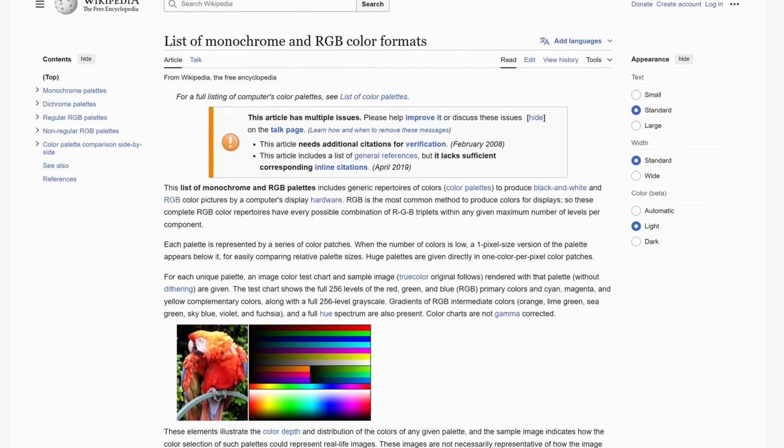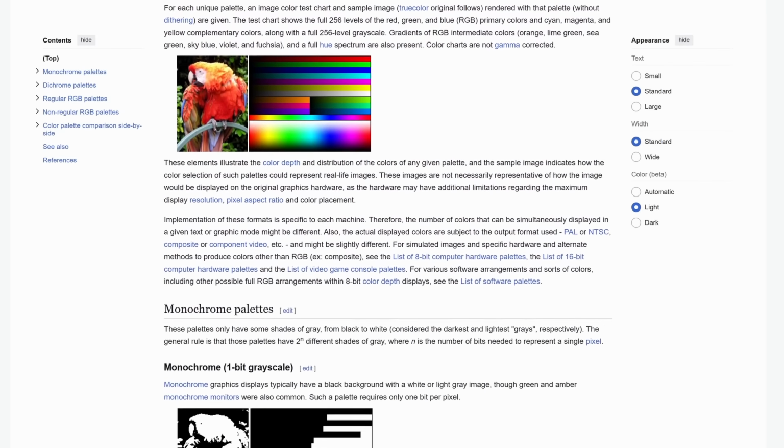There's also a lookup table approach called L8, where your frame buffer stores 8-bit values that correspond to RGB 888 or RGB 666 colors. And finally, monochrome displays can represent grays with up to 8 bits, but you'll often find it's just on or off, a single bit per pixel. There are a lot more color formats. Wikipedia has a whole page on them if you're bored.